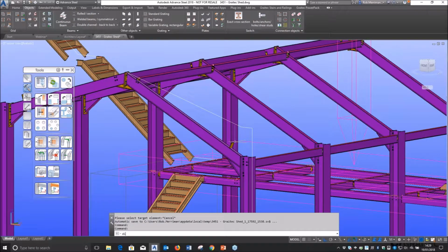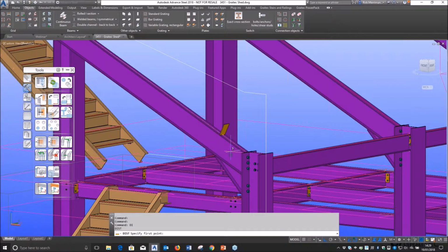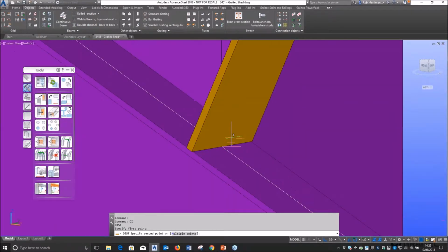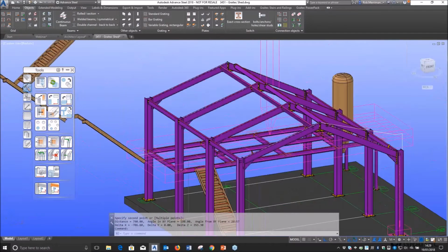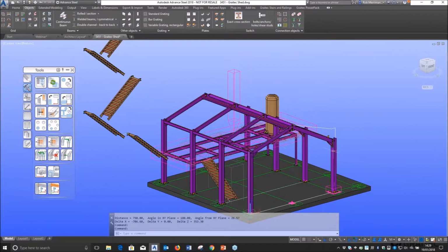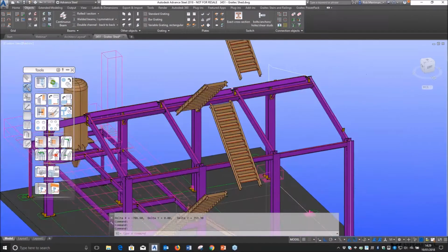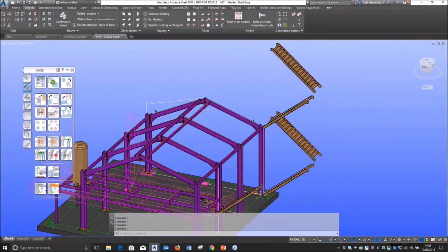And if I did a distance from the node in there to the node point in there, I've got 790, so to the back of the plate it would be 800, so it matches on both sides. What you need to be careful of with this tool, because sometimes it will work, sometimes it won't work for you, and you'll be potentially wondering why.